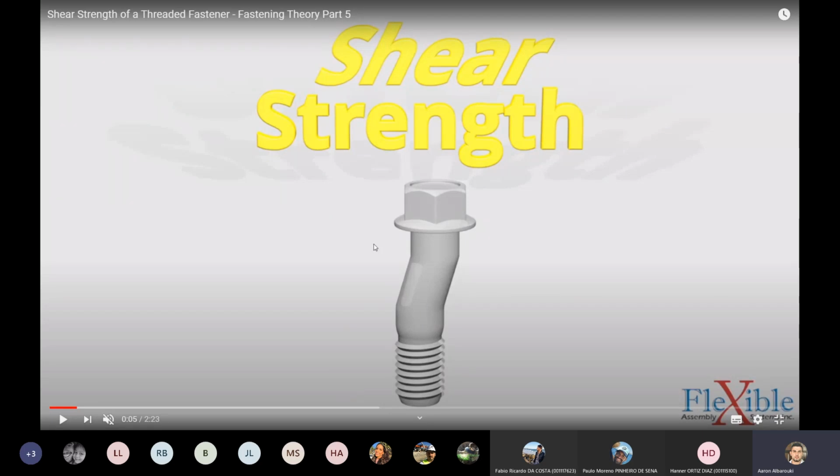If I draw the force here, the force will be this way here and that way there, pushing the bolt. If you look at these forces, both are parallel to the cross section of the bolt. If this is the cross section, the forces are parallel to this cross section. So this is a shear stress, not a normal stress anymore.